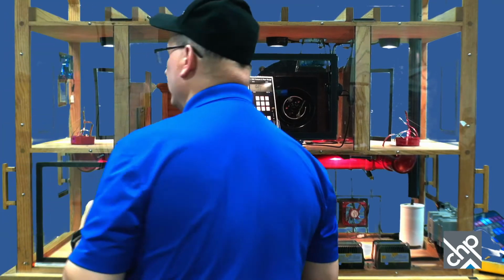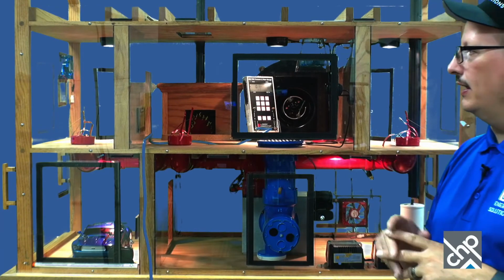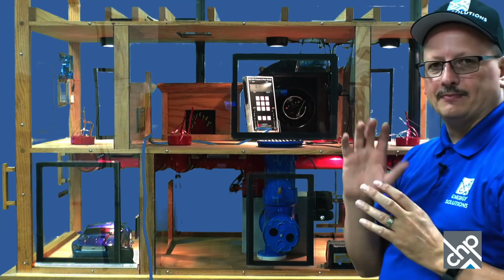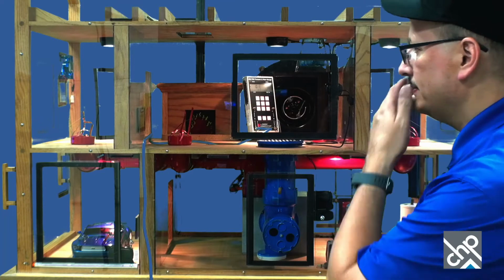And got everything set up there. And so what we want to do now is think about a typical CAZ combustion safety protocol. Like I say, you've got it in winter conditions or natural conditions. You did your baseline. Now you're ready to turn on your exhaust fans and see how the pressures get affected. And then we'll go through some door closure, air handler, that kind of stuff.